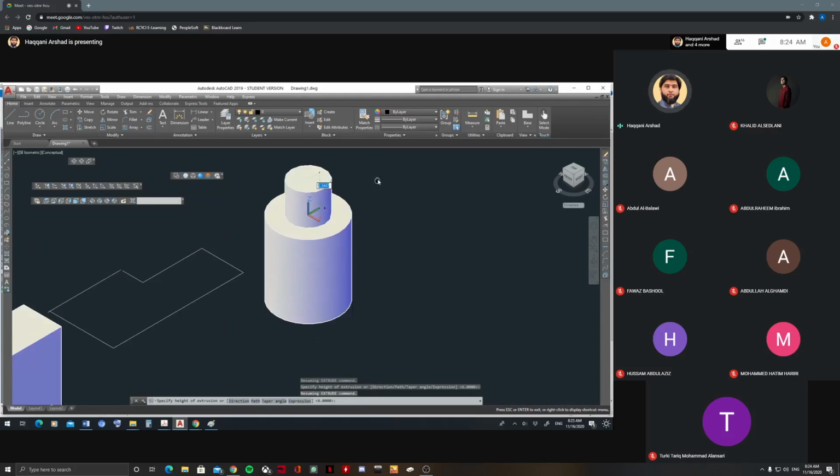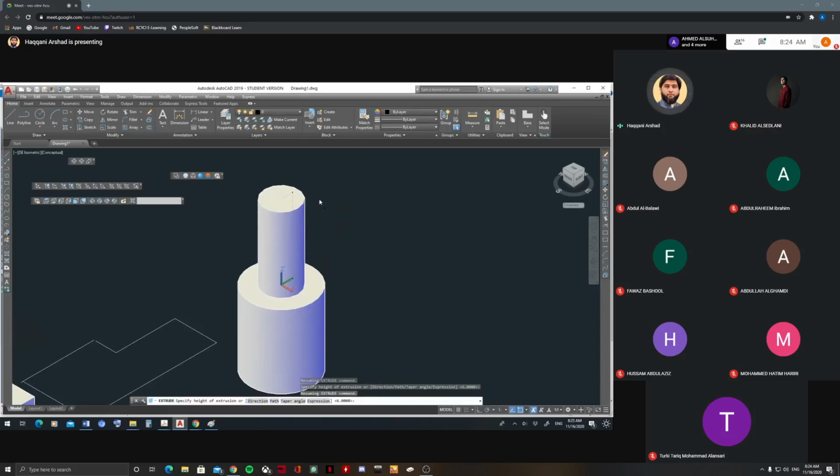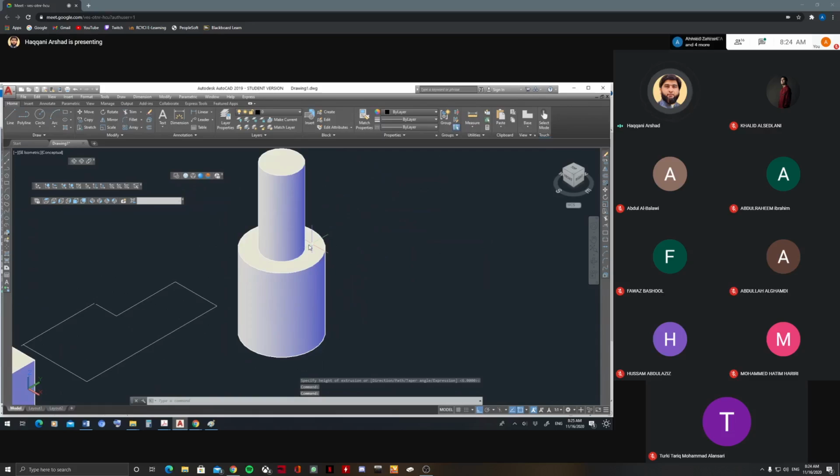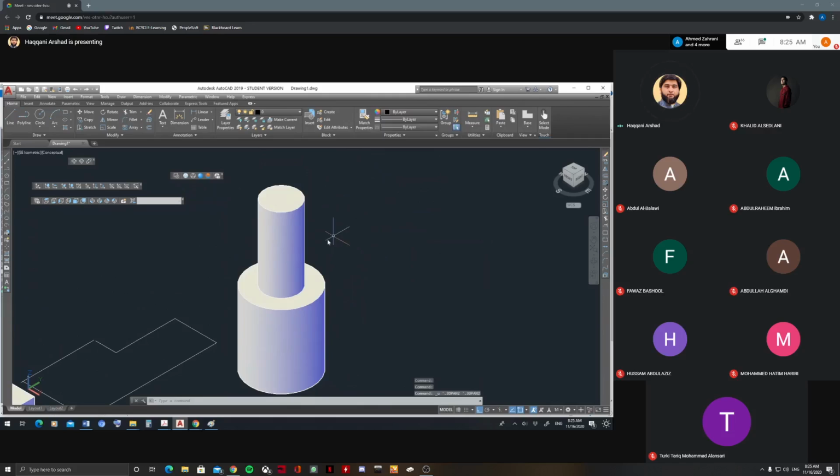So in order to make hole, you can do extrude, but I want to cut this hole from this big cylinder, so I have to extrude in the minus direction, like this direction, not like this. If I put like this, it will be another cylinder. But I want to make a hole, so I have to pass through this. I cannot trim this. So I'll go back.